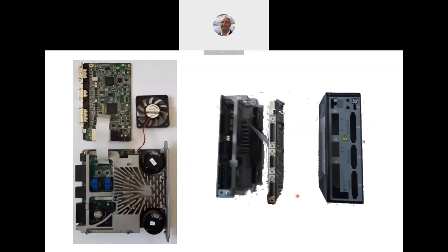Okay, so as I told you, many of the book mount, okay, that's what I call book mount. It's the servo drive you put in a machine, has a control board, heatsink frame, and the power stage. Here you can see the heatsink. That's the control board, and that's the flat cable. The only information mainly is the PWM to UVW and the Hall sensors back.